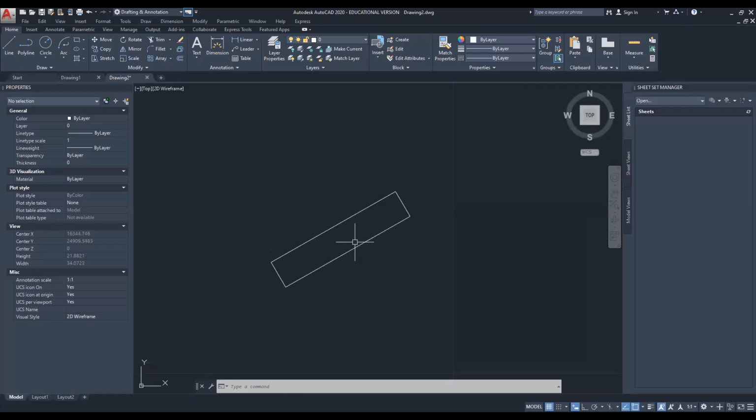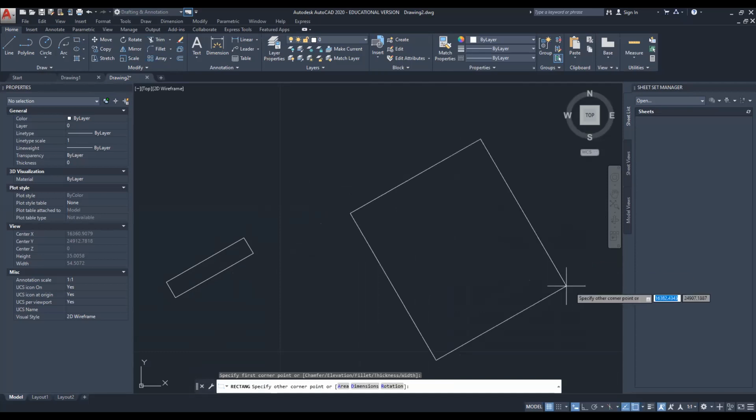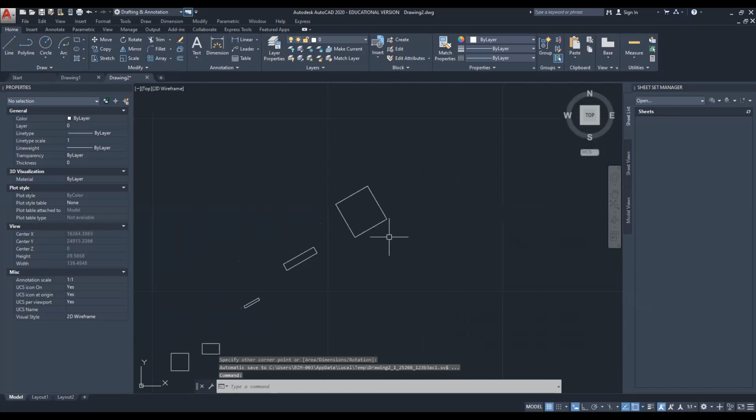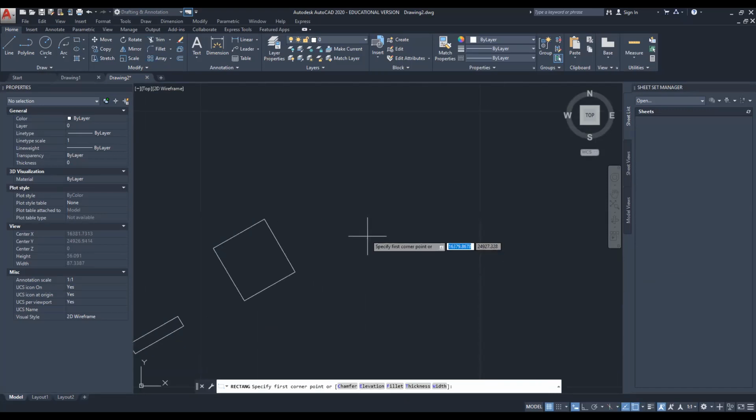But you can see that the rectangle that I have created still has some rotation. But I don't need a rectangle having some rotation value. I need a common type of rectangle, a horizontal rectangle. So if I select this rectangle tool again and create a rectangle, I will always get a rectangle having 30-degree inclination. So for changing that to normal, we need to select the rectangle tool again and we need to go to the option rotation again.